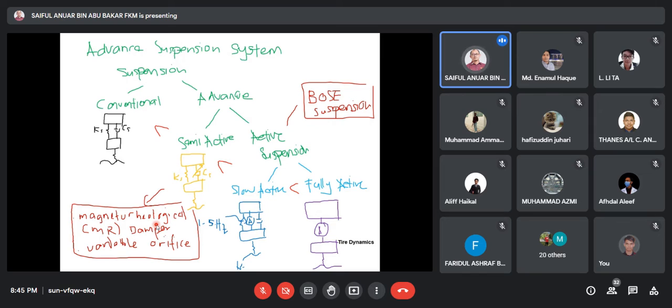Again, you can see videos of MR fluid or the MR damper on YouTube, where you can see the fluid hardening. It changes from liquid to semi-solid, and then from semi-solid back to liquid, and you can see the differences when it's introduced to a magnetic field. These characteristics are manipulated inside the shock absorber, where we introduce the magnetic field at the orifice, the opening where the fluid needs to go through.